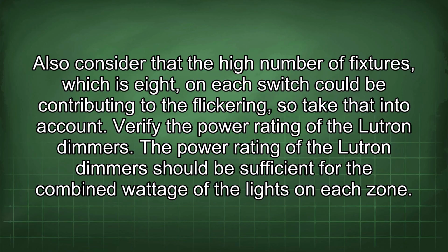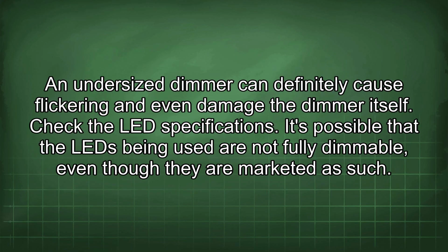Verify the power rating of the Lutron dimmers. The power rating of the Lutron dimmers should be sufficient for the combined wattage of the lights on each zone. An undersized dimmer can definitely cause flickering and even damage the dimmer itself.